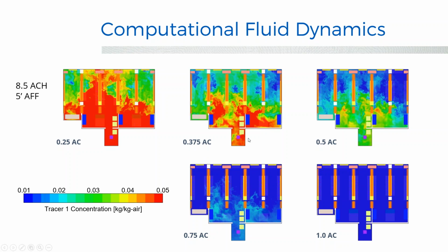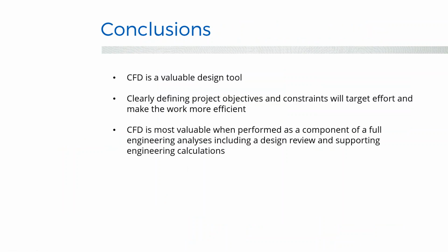So yeah, at the end of the day, we were able to show that under the majority of operating conditions, we could run at 6 air changes per hour. And then at peak loads, they could ramp up the cooling loops within the chilled beams to help handle the thermal loads. So this is also a good story.